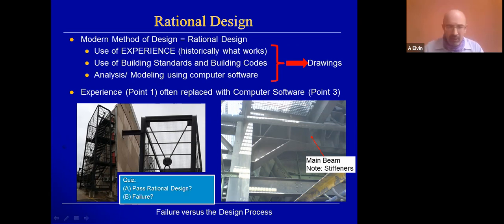All right, so let's have a look at what I have on my slides. Nobody has written that it's unbraced in the direction shown. This happens to be an exam question that I used to set quite often, and most people do not pick up that the structure is portal framed in the wrong direction and it's unbraced in the weak direction, and therefore the entire structure does not pass rational design. Now, has the structure thus failed?